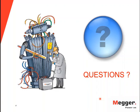If you are doing an operation in the field, and let's say that you don't have an LTC, a load tap changer, but you have only a DETC, I would suggest you first ask the operations owner and discuss if that DETC has been exercised before. If the unit had the DETC in one position for a long time and that DETC has not been exercised, I wouldn't recommend you to move that one. So you will test only on the operational position.